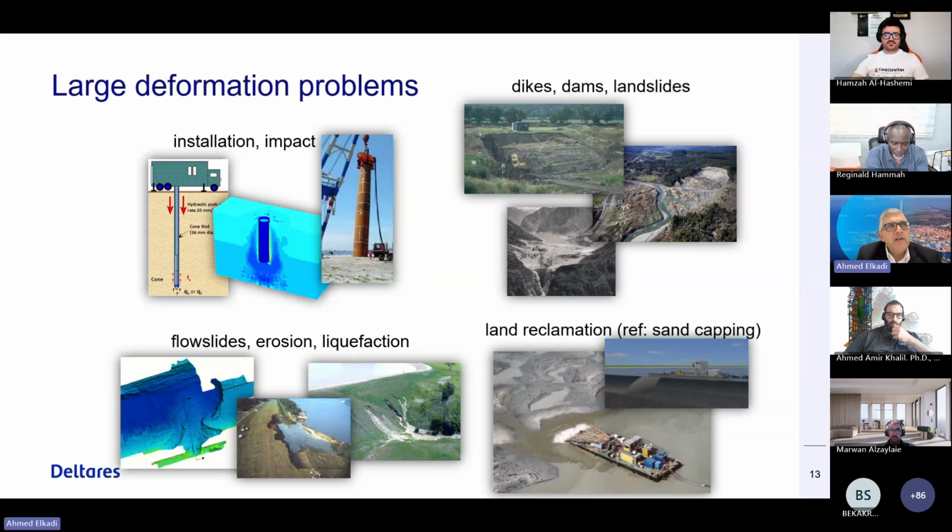That's offshore type of piles for offshore wind, and we actually succeeded in modeling the installation phase, which is usually not handled, because we're dealing with piles, if I may say, a pile in the order of 10 to 15 meter diameter, so it's a really huge structure. And the installation effects play an important role in the loading capacity of these piles or structure afterwards.